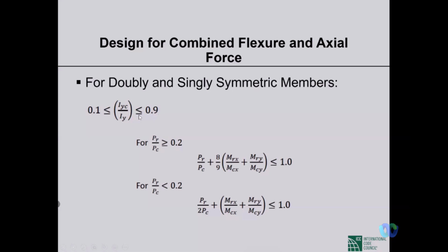So it always satisfies most of the time. If it satisfies, then if the required strength is more than 20% of the available capacity, then we have this expression which has got a factor 8 by 9, and then if it is only 20%, then the expression is a little bit different.